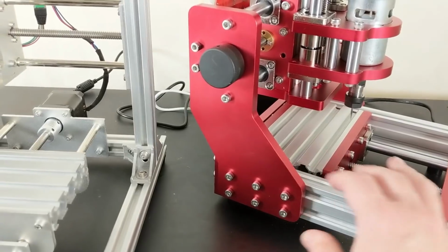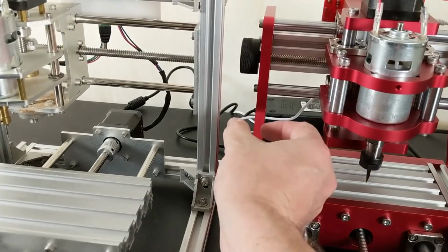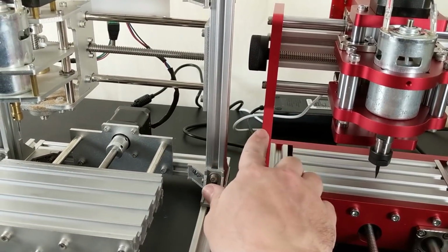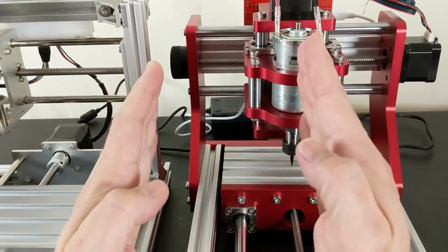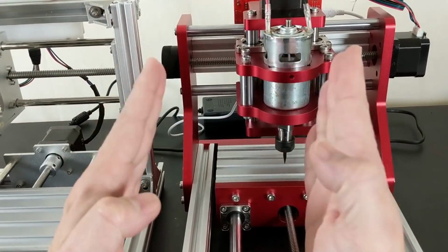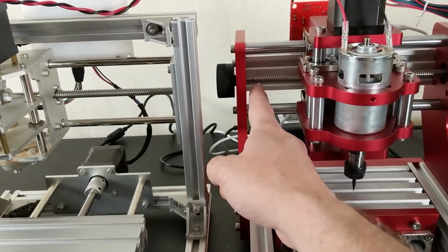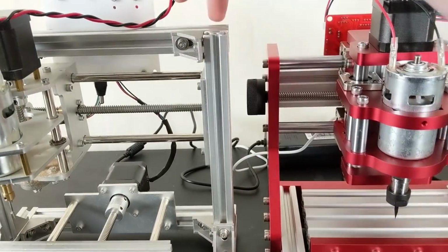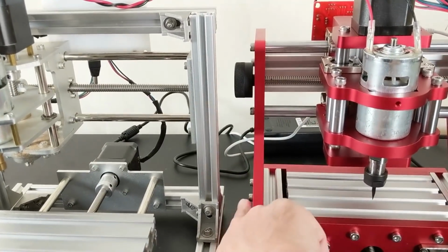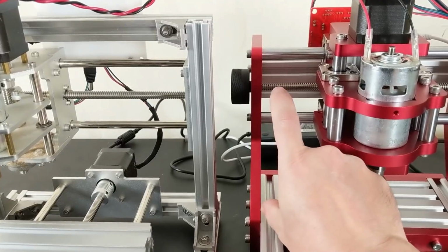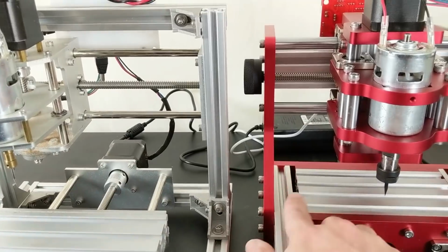So we're already stiffer there, but the problem with this machine here is the 10 millimeter thick plate is still half as thick as the 20 millimeter thick extrusion there. So theoretically, this machine could flex in that direction. But not so fast, because what we have here is some more of that 40 millimeter extrusion with 2 bolts holding it rigidly to the plate, and then of course the 6 bolts there, which means that we have a rigid frame going on here, and that is not a very long distance between those cross members.